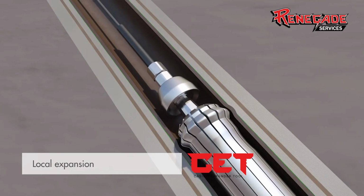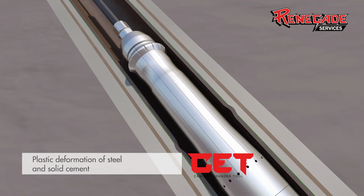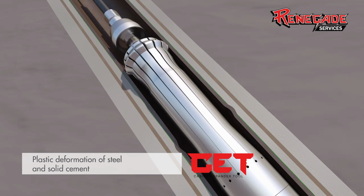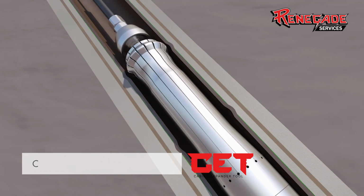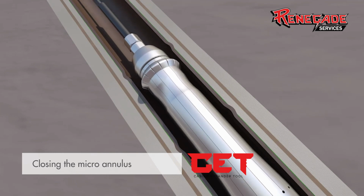Now the pressure of the ring on the cement will cause the cement to actually locally densify. Now that should close off any gaps or small channels within the cement. And one thing to note is that this is all plastic deformation, okay? So without getting too technical about that, literally that means that it produces a permanent change in the shape or size of an object, but without fracture.